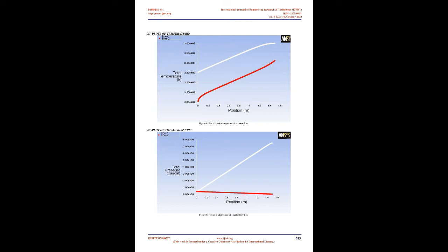4. CFD analysis. Computational fluid dynamics, CFD, is the study of a system that starts with the construction of the desired geometry and mesh for modeling the domain. Generally, geometry is simplified for CFD studies. Meshing is the discretization of the domain into small volumes where the equations are solved with the help of iterative methods. Modeling starts with describing the boundary and initial conditions for the domain and leads to modeling of the entire system. Finally, it is followed by the analysis of the results, conclusions, and discussions.